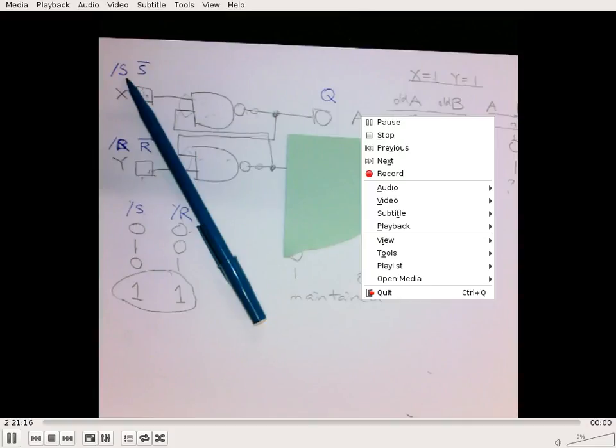But the best part is you can now have multiple things like this to trigger the reset. If any one of these transistors thinks, oh, okay, I gotta reset the circuit, each one of these can reset the circuit independent of the others, and there's no fight whatsoever. Because the only thing it has to fight in order to bring this line to 0 volt is this resistor here, which is a very high value resistor, which means we have a lot of resistance. So it's not really having a lot of strength pulling the signal up to 5 volts or VCC.